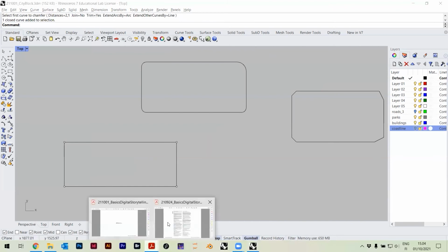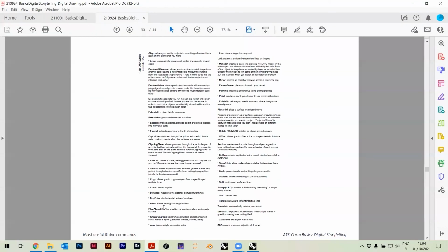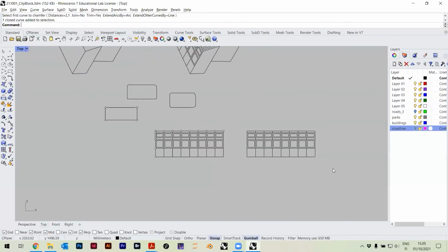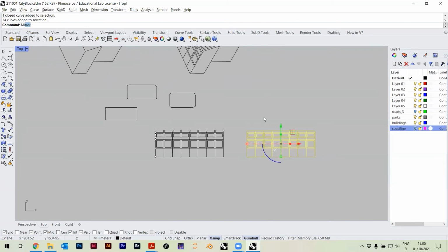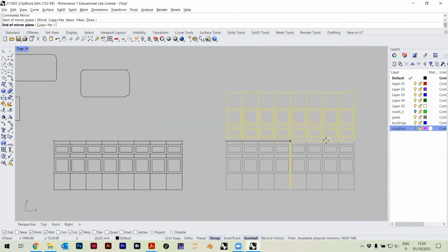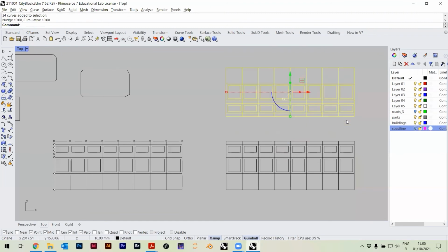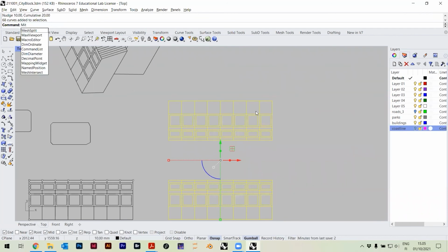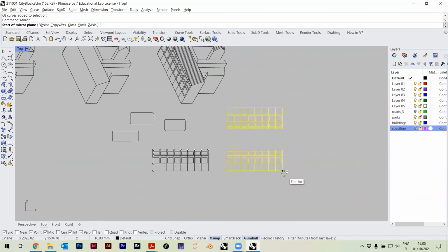And just quickly go through some of the commands here. Group, ungroup, line I showed, make 2D I will show some other time when you need to work with three-dimensional geometry. Mirror, I think I showed once. So mirror is just mirroring the object. For example, I can select this one, I can say mirror, then I select the mirroring plane, and that's it. I get the same thing, just mirrored.